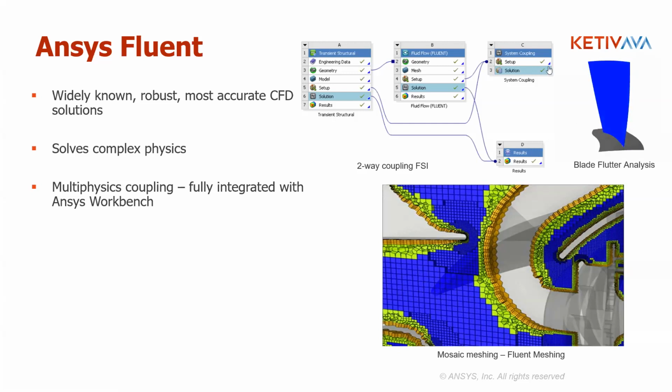On the right here, you see the general workflow of simulations in a platform called Ansys Workbench. It is the general area wherein you couple all your different simulations together. So for example, you see here a structural simulation and a Fluent simulation, and see how the solution from the structural and the Fluent solution have been fed into a third workflow, which is called system coupling. Now, both these simulations can be handled iteratively, or they could be solved simultaneously.